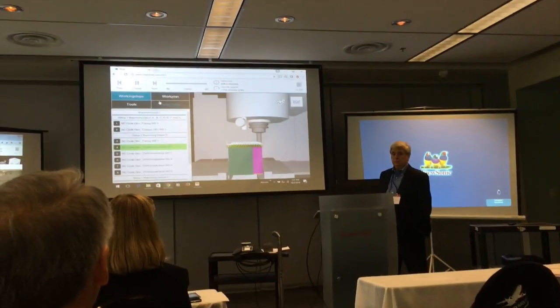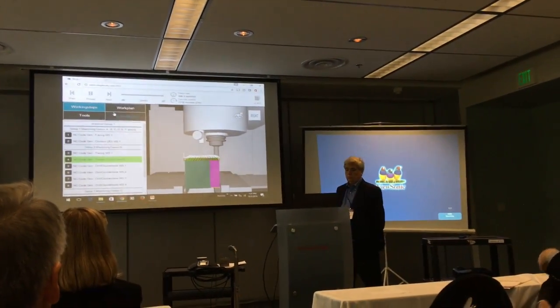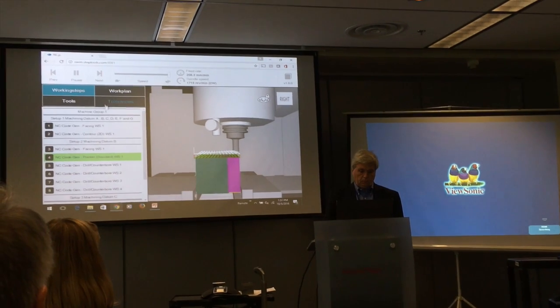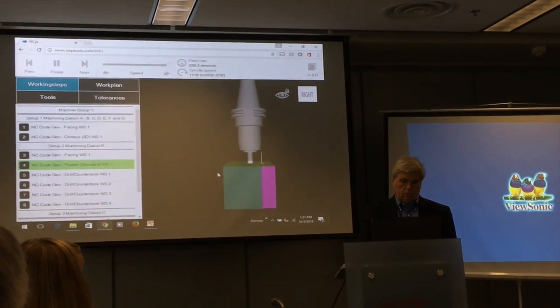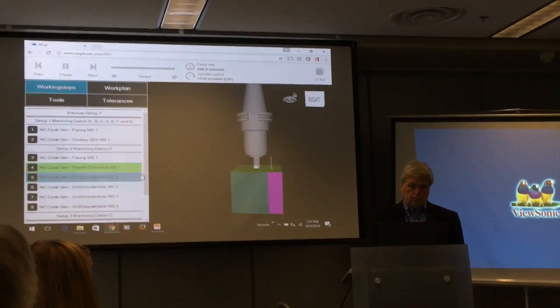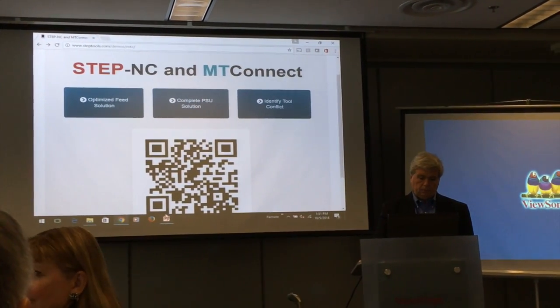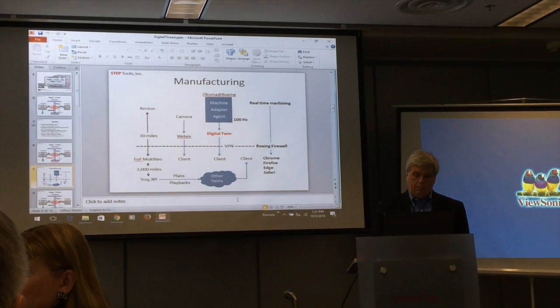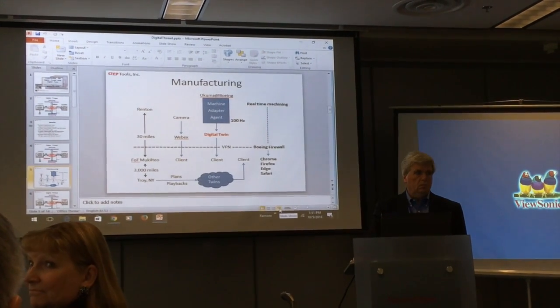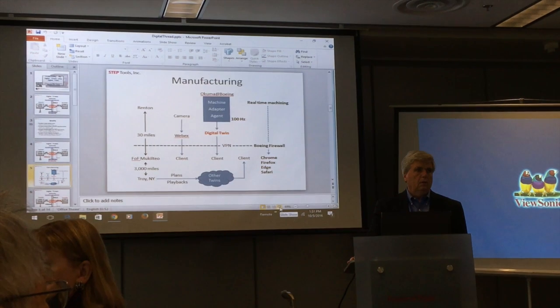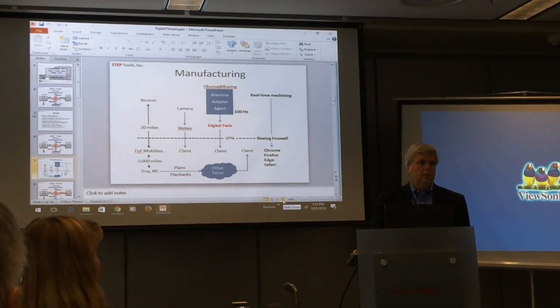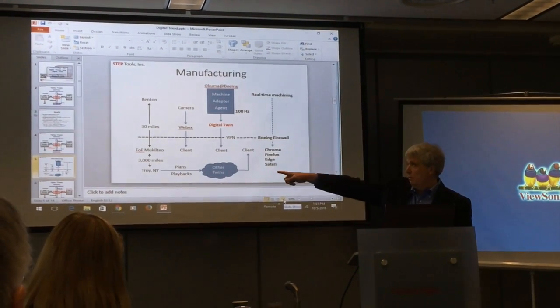But not through MT Connect. You wouldn't typically transmit base machine capabilities through MT Connect. You would use 242 to do it. But if you wanted to know what the active spindle horsepower or RPM was at the time, then you use MT Connect for that. Am I getting this right, guys? The real-time data. Yeah, the actual data comes through there. Yes.